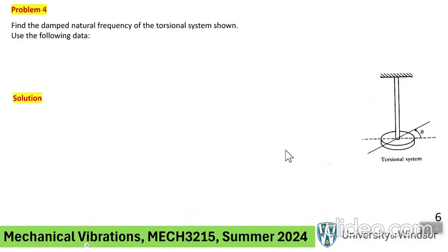We're going to solve this problem. This is also essentially a mass spring damper system. Assume there is damping, for example. The only thing is it's a torsional system. So this shaft, with the appropriate dimensions and the shear modulus material properties, will give us a stiffness. And we have done that before.